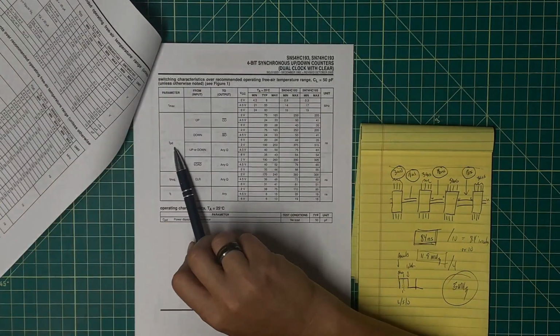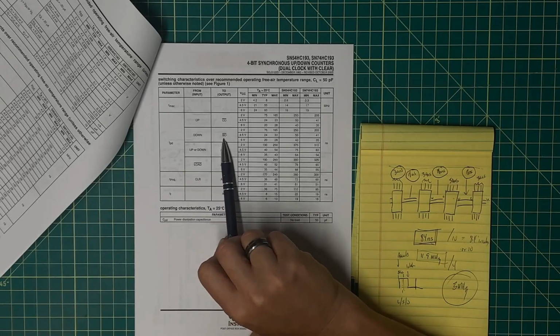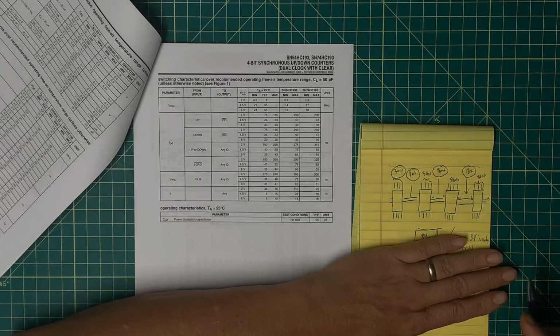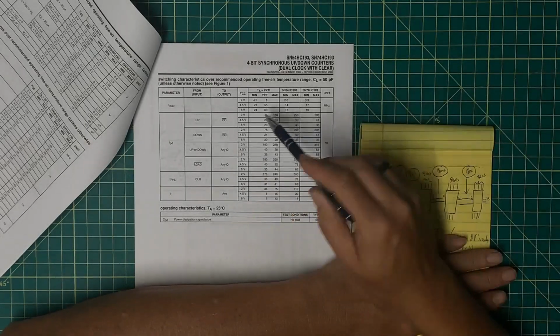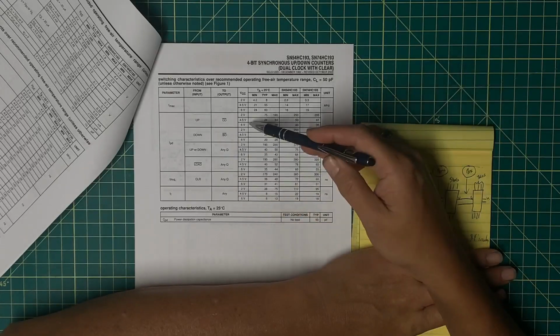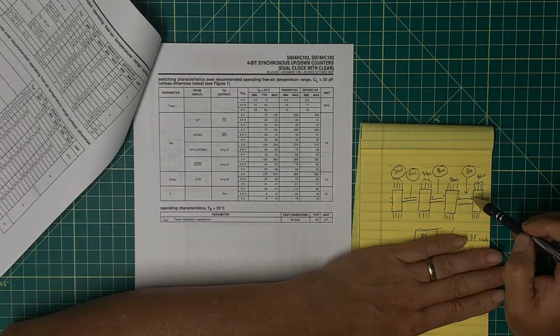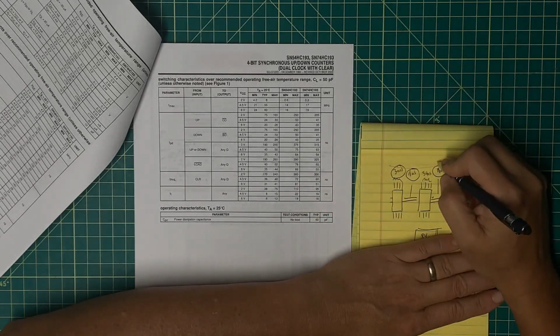Here is our propagation delay, for an up count to the carry out, a down count to the borrow out, or up or down to any Q. So given our diagram here, again, let's redo this analysis. Running at, and I'm going to pick on 4.5 volts, from the up count to its carry or down count to its borrow, that's 41 nanoseconds.